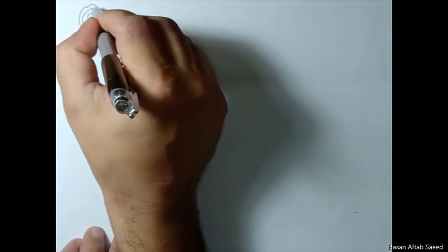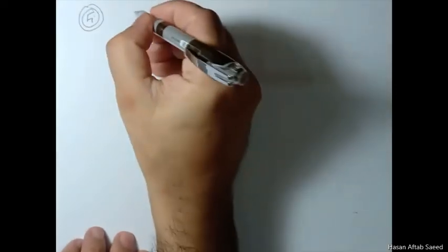If Fi is known, and we are assuming that Fi is known, we want to apply this much pretension, and we'll come to this later on when we study the static and fatigue loading. If you know this much preload has to be applied to a nut bolt situation, what kind of torque do you need?